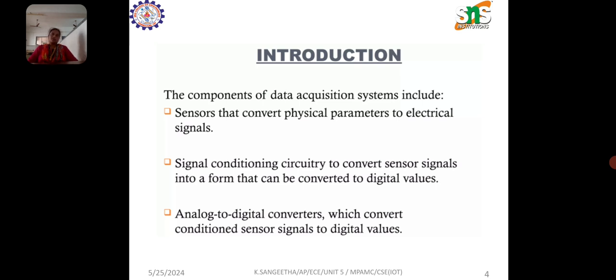And data acquisition hardware houses the ADC, multiplexer, and possible signal conditioning components, and a computer or embedded system collects, processes, stores and displays the data. This can be a PC, a DAQ controller or an embedded system. And finally we use software to control the DAQ hardware, configure measurement parameters, acquire data and perform analysis. Examples: LabVIEW, MATLAB and Python libraries are used.